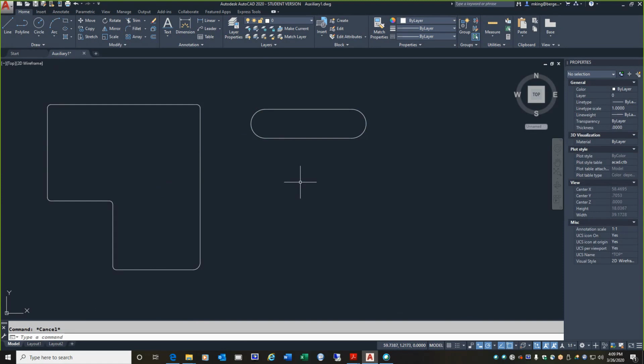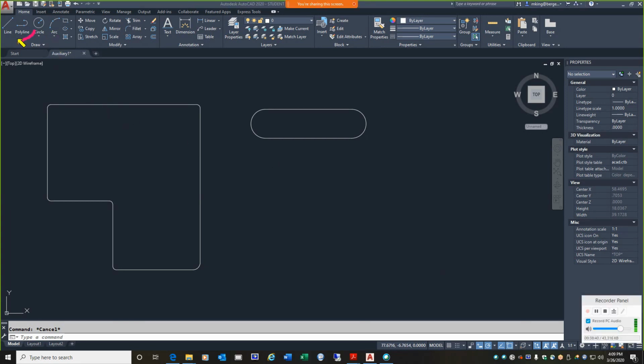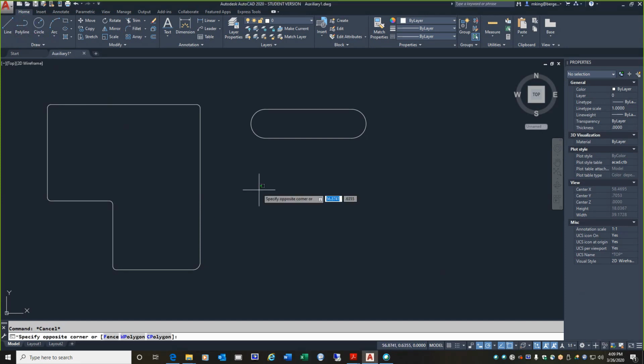Okay, another thing that polylines can do, I can have a line show thickness. I can automatically draw using thickness. Okay, so let's do that. So step 1, go back and pick polyline and select somewhere on screen to begin your polyline. And once again, look back down at the command prompt. The command prompt has some options. This time select width. All right, I'm going to pick W for width. And I'm going to say 0.25, enter for starting width.